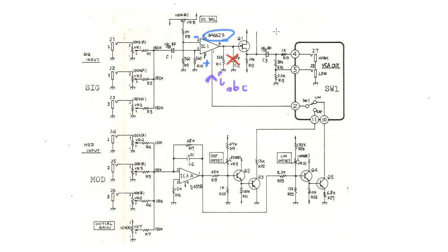Notice that you don't actually see a microfarad written here, but in the kind of circuits we're looking at, if they don't write a unit for capacitance, you can assume it's microfarads. If it's something else, they'll indicate that. So I'm not going to bother analyzing the effect of those. I've been implicitly assuming that those were short circuits the whole time as far as our analysis is concerned.